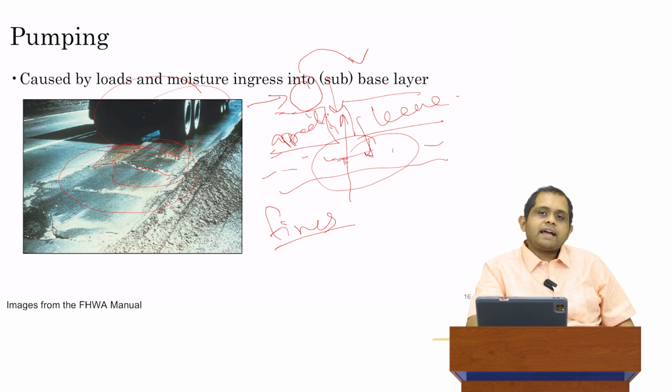If you have these cracks and moisture, but in a low volume, that is, you don't have very heavy traffic, then you may not have pumping. So in a way, pumping is related to climate. It's related to rainfall in this case, but you also require these heavy loads in order to cause enough pore pressure to develop. So pumping is somewhere in between being caused by only loading or only being caused by climate.